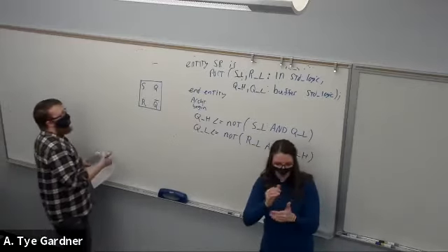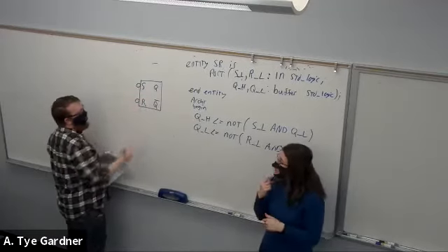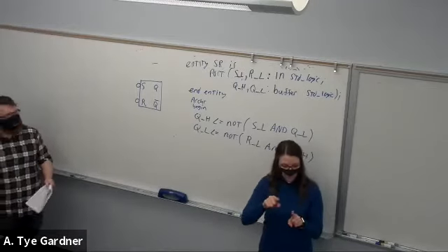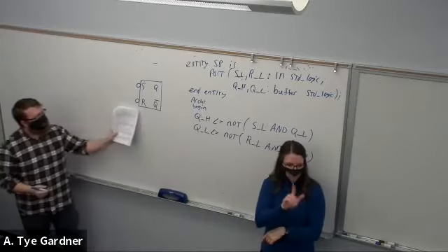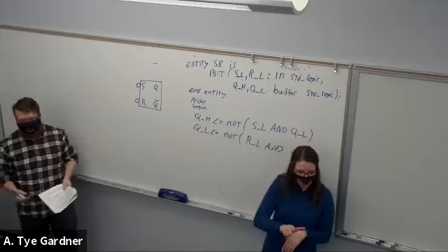And it also gives us a lot of flexibility on how we want to design it. So let's say I want an active low set and reset. I just add inversion bubbles at the inputs, right? Now, that's exactly what we talked about here. That matches the code. Active low set and reset, Qs come out.